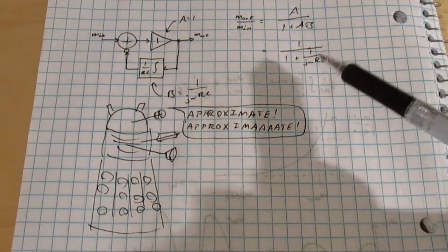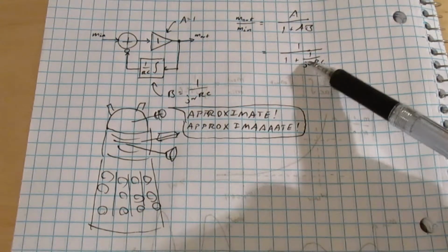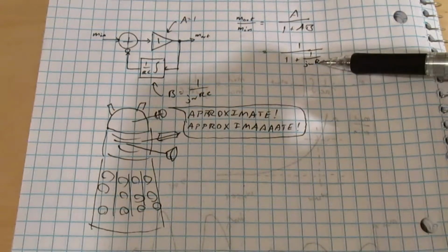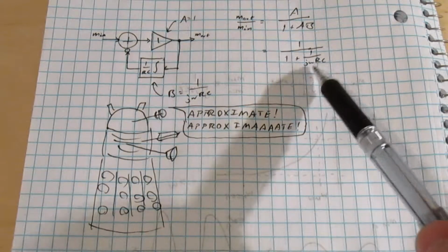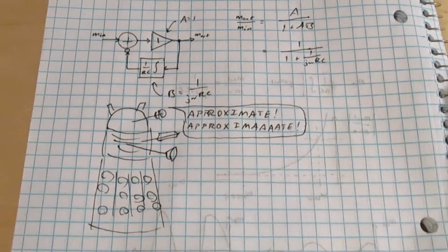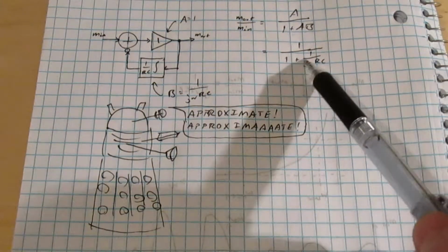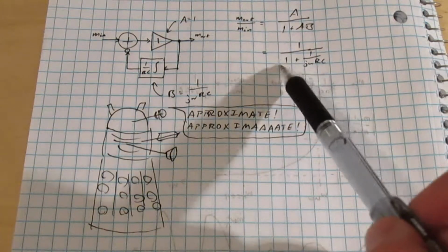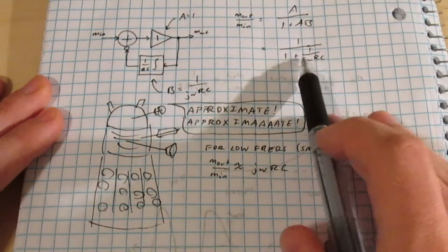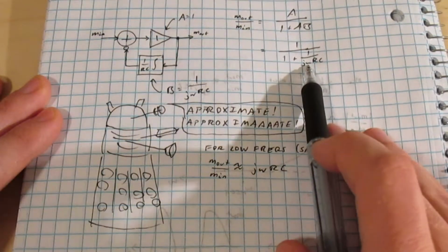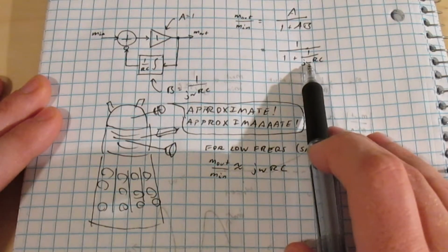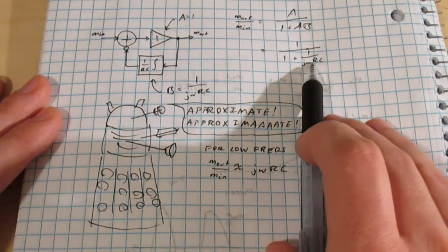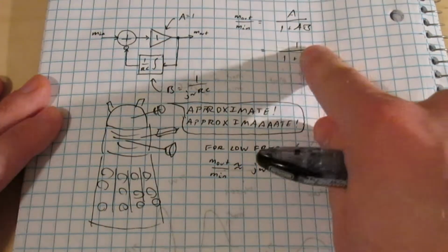So if we think about what happens if the frequency is low, which means omega is small, we have 1 over a very small number. And 1 over a very small number ends up being a very big number. And a really big number plus 1 is really not all that much bigger than it was before. So we can say that when the frequency is small, then this term, the 1 over j omega RC, is the dominant term, and we can just ignore this 1. And when the frequency is really high, this term turns into 1 over a really big number, and 1 over a really big number is a really small number. So if the frequency gets high enough, and this number gets much smaller than 1, we can just ignore it and pretend it's not there because it doesn't have much impact on the overall result.